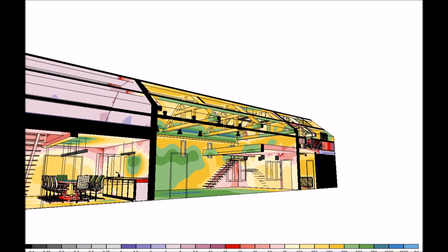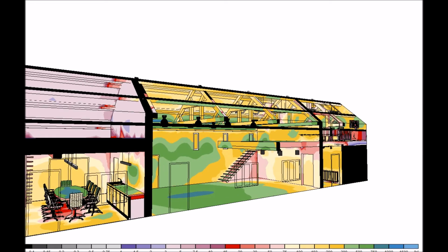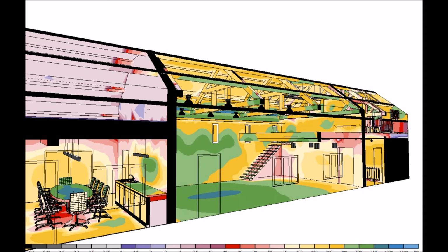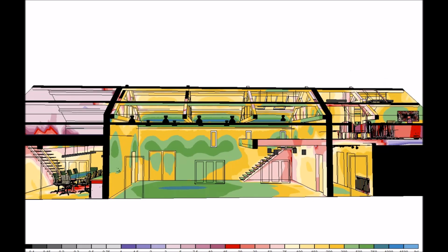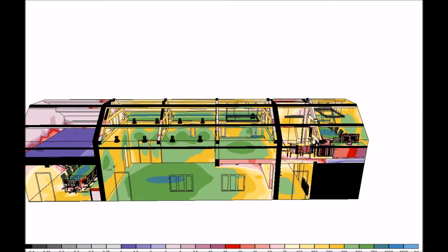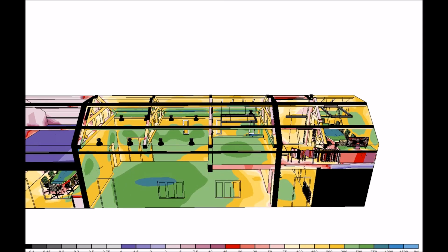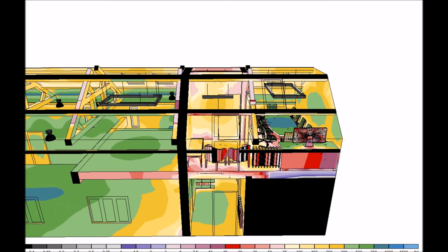The meeting room is a little bit on the higher side, which is why I couldn't decide between 2 or 3, and that can be decided later, or we can try and modify the output to suit. But really, getting the style agreed is what we want to try and do. Mezzanine again, it's a good level of illumination for the desks. The waiting room in here, it's a comfortable level, just between 200 and 300 lux. The entrance here, yeah, it's a good level for the entrance.